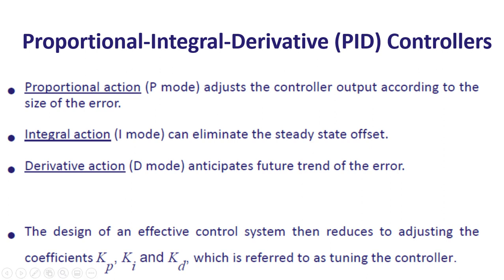So if you have some constant error, then you can introduce integral that will remove that steady state error. Why does it remove it? Because when you introduce integral in the system, it will increase the type of the system. So if you have a constant error in the previous type, and your type is moved to the higher side, your steady state error is 0.